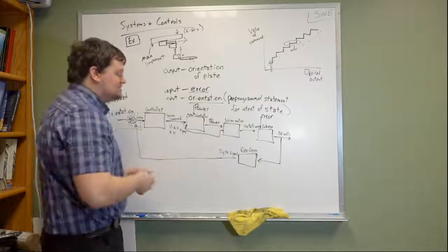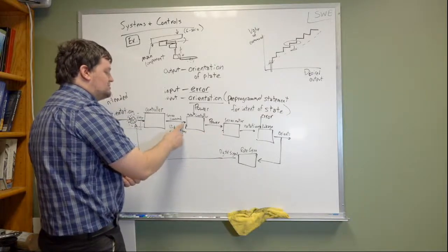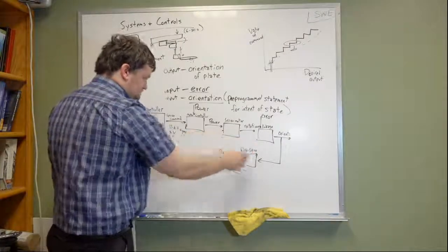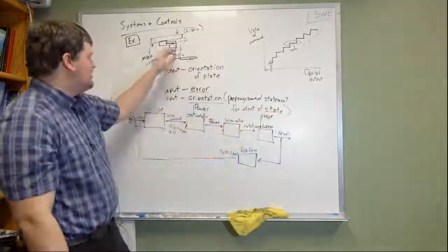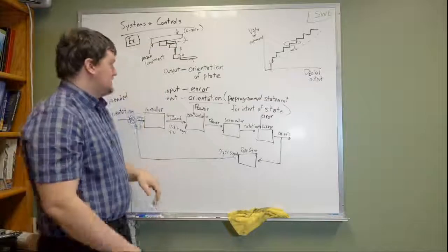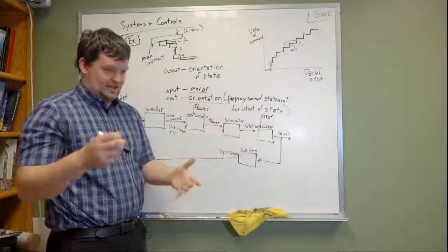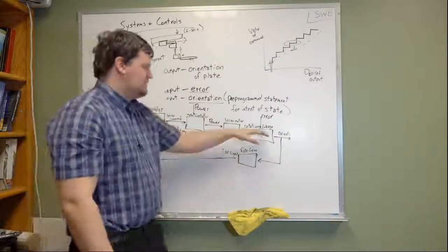So here we then have error that's being propagated through. That error is a result of the fact that these are real components and not ideal components. You have that type of error. You have this type of error, which is usually a force, a rotation, 6-axis input that's being put into this linkage to indicate how this is shifting, how it's moving. So you have this type of error.